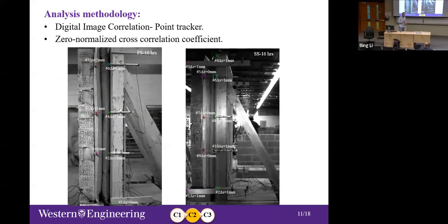For the video that we recorded with the high-speed camera that I talked about, we recorded the video for DIC analysis, or digital image correlation. But at this stage, I used just the point tracking data to modify the data recorded by LVDT, because we assumed that the wooden frame was a self-standing system and there wasn't any deflection in the frame. So we should prove that. Based on the videos, we did point tracking to find out the displacement that happened in the frame, to deduct that displacement from the LVDT data to ensure that those data are correct. Those are regarding just the displacement in the wall.